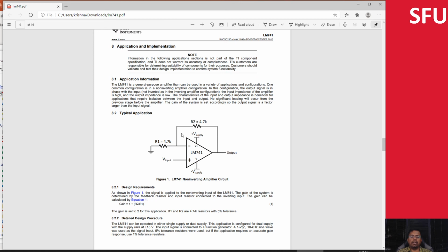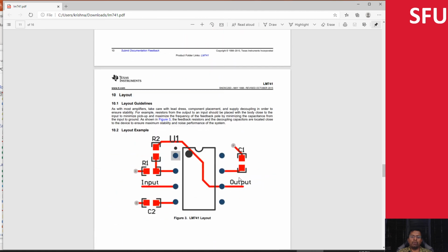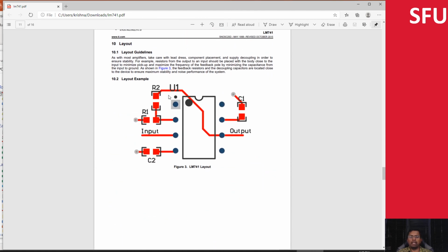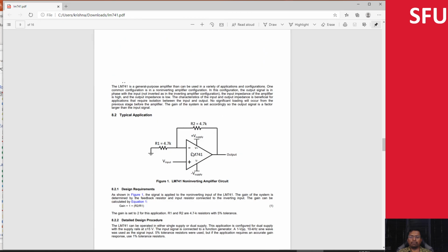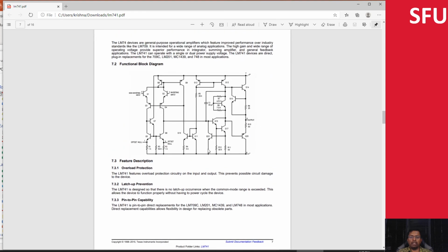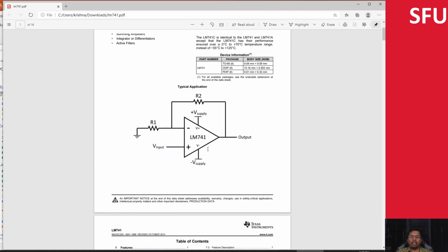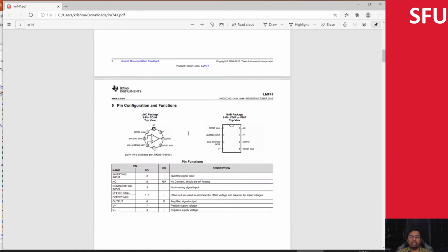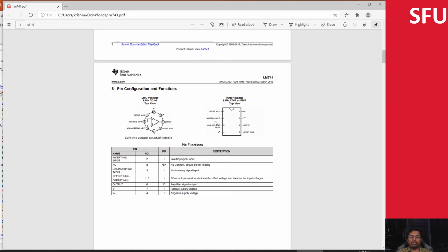And then this is the example that I basically have. The symbols for V plus and V minus are a little bit different, but nonetheless, we can use the circuit. It also gives you the frequency range and the typical layout that they recommend. So this one doesn't really have a pin associated with it, but you need to go back to the drawing and it'll tell you how the pins are laid out. Here it tells you this is null offset, this is converting and so on, and based on that you need to map it and figure out how the circuit is looking.